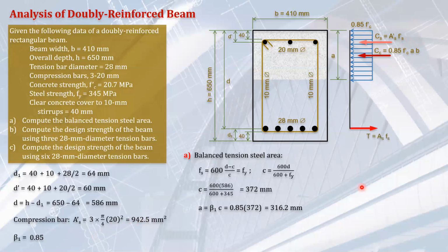And then the tension in the tension steel here. Well, if you're computing the balance, automatic, yung Fs mo is equal to Fy. No? So sure na yan. But I will just write it first as Fy, or as Fs. Okay? So alam natin, in this case, letter A, that should be equal to Fy. Kasi balance steel tayo. Fs equals Fy. Alright, so by the way, ito yung moment arm, D minus D prime. Ito naman yung moment arm ng compression bar, I mean concrete, sorry. Ito yung sa compression steel, D minus A over 2.